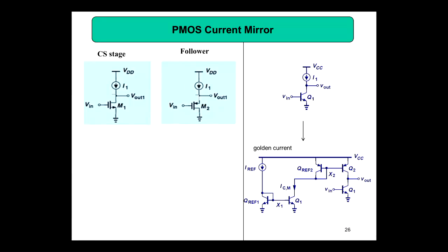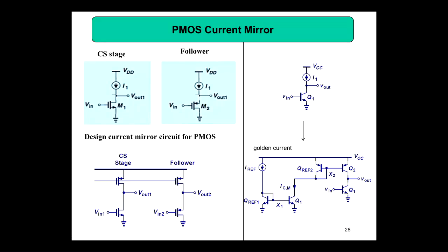So this is a common source stage and follower stage. Then if you want to bias it here, now the arrow is here, the load resistor is here. As I said, we need a PMOS. Then here also you need a PMOS. So that's the reason here we are replacing these currents with PMOS, pretty much like this. And then we have to provide another PMOS transistor for the current mirror. Then you need another NMOS current mirror to bias your PMOS current mirror.